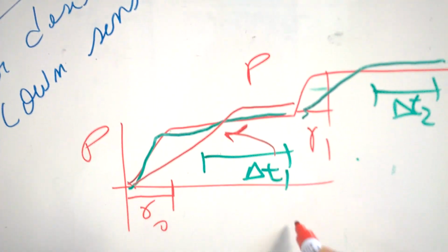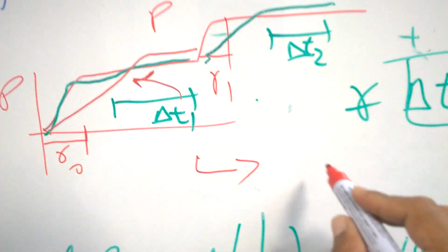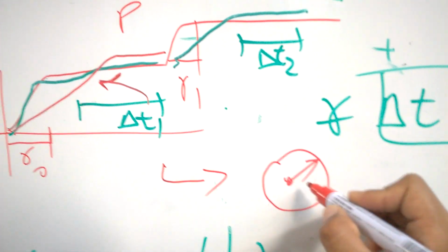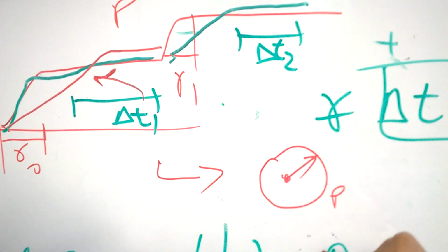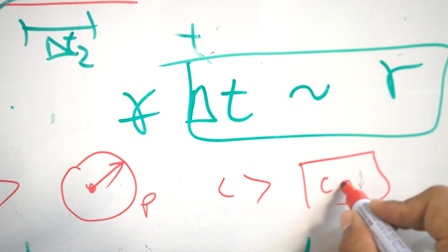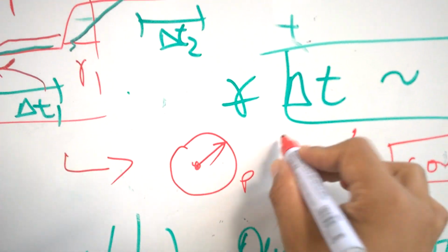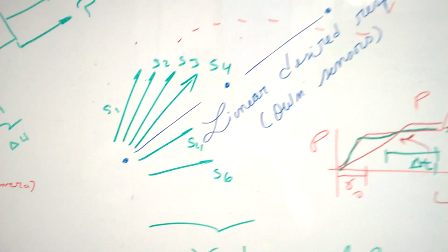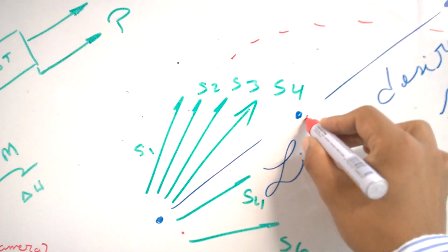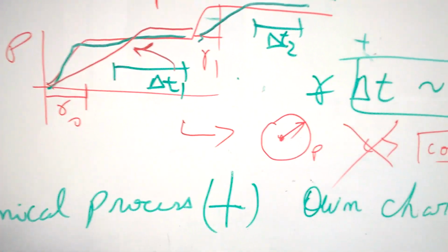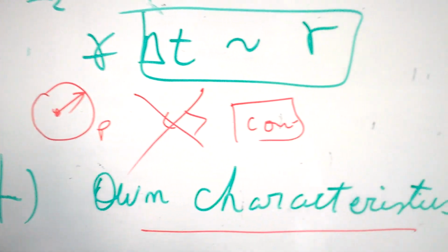And you can check these troubles because when you see the sensor, for example, the pressure level in the bulb, and compare it with the computer, of course it will be different. But why? Because we didn't linearize the system? Because we didn't obtain correctly the offsets from this point to this point? What happened? This is the trouble, because of all the characteristics of the system.